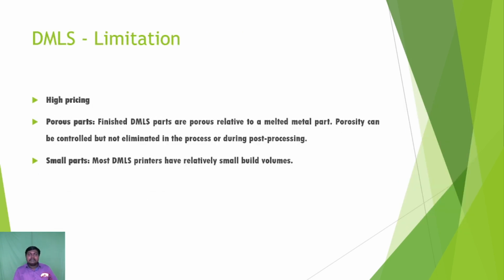The limitations of DMLS. The price of the DMLS printer is very high, and the finished DMLS parts are porous, related to a melting metal part. Porosity can be controlled but not eliminated in this process during post processing.